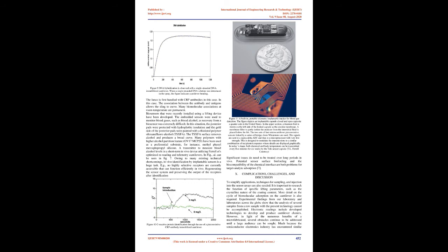Micro-cantilever beams are particularly sensitive sensors to displacement. Because there is no inherent chemical or biological selectivity, highly sensitive receptors on the cantilever surface are often immobilized to gain identification selectivity. The selectivity of the recognition is therefore dependent on the selectivity of the receptor. Many strategies were used to immobilize molecular detection agents on the micro-cantilever array. Thiol chemistry is a commonly used mechanism by which receptors may be inserted.